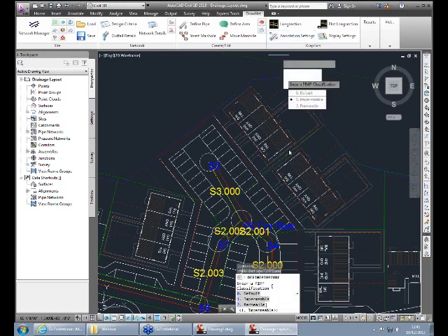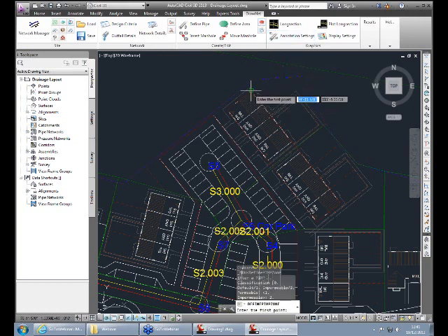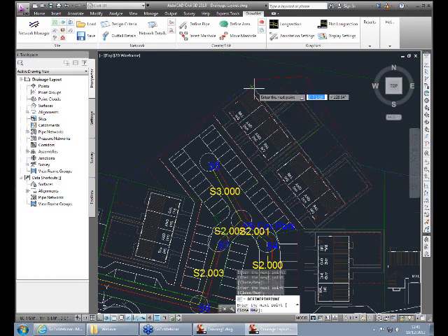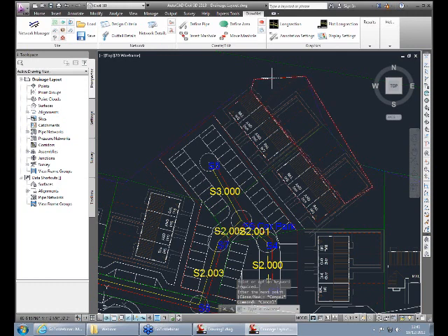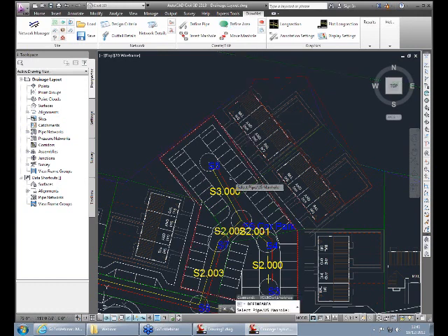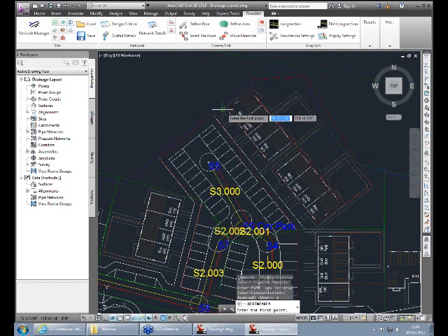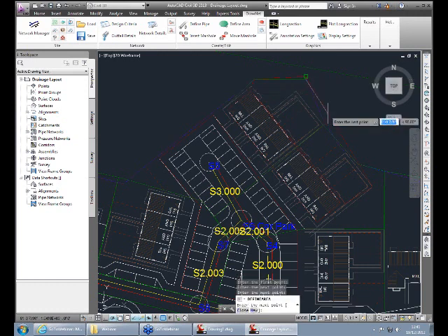I then set up a second one, which is a permeable area. So I put in the gardens in the back. Roughly, and again now I have the second part of that house plot with 40% impermeable. I can now, with those two set up, define my areas. So if I was to define the area getting into this manhole, use as zoned, and then select the whole plot for this upper one.